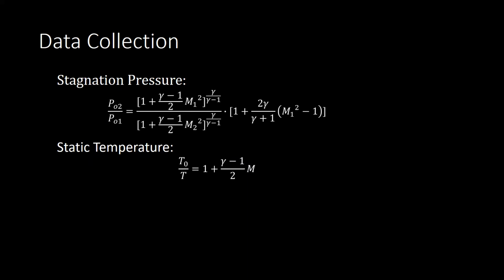Finally, these forces and measurements are taken with a variety of sensors or other tools such as a pitot tube. You have pressure sensors, thin film sensors, thermocouples, everything like that. And like I said, with hypersonic flows, you're moving at much faster velocities, so you're going to need better equipment in order to handle this very rapid change in difference between subsonic and hypersonic. And from all these sensors, you can use these equations and, like I said, backtrack to get any fluid property.